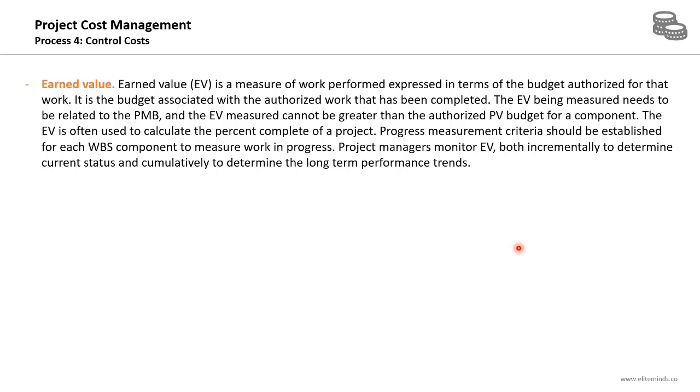So if you have a story in a construction building, one floor should cost you $200,000, and today the value of the work completed on this floor is $150,000. The $150,000 till today is the earned value. The planned value is the $200,000. The earned value is a figure you will obtain from the work performance data in the project. It is expressed in terms of budget. It is the value of the physical work that is actually completed on the project.